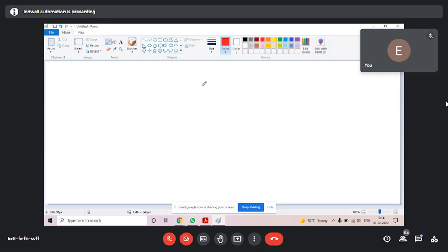How do you see? Flag is a bit memory, output is also a bit memory, correct? Flag M is a bit memory. Q output is also a bit memory. This will also get on and off. This will also get on and off. So similar. In coil we can use output address, but we cannot use input address. Input address, sorry, once more. In coil we can use output address, but we cannot use input address. That is clear, no? In coil we can use only output address. Input address cannot be used in coil.